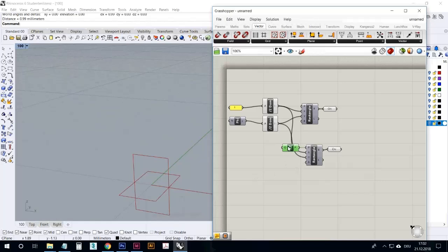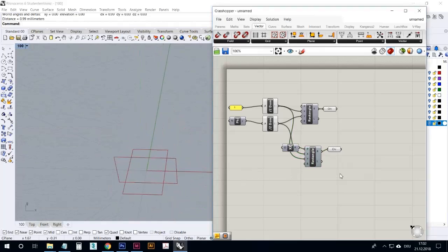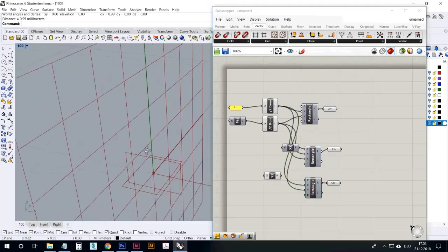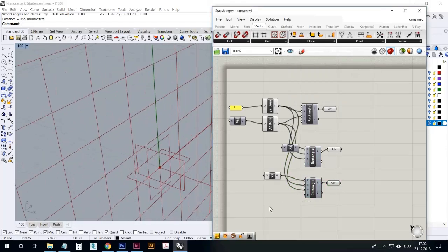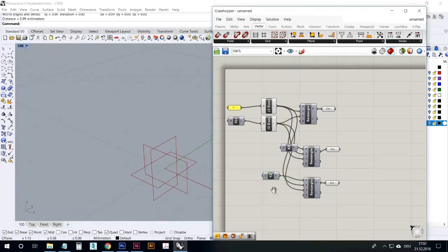It is simply a matter of swapping X and Y. So we swap, and there you go. Now they are combined. So we can copy the first one again here to get the third rectangle, and you already know probably which plane we're talking about then, with the YZ plane. So now you draw in this direction. This time it is going to be correct also with the rectangle there. Okay, so we have the rectangles already.